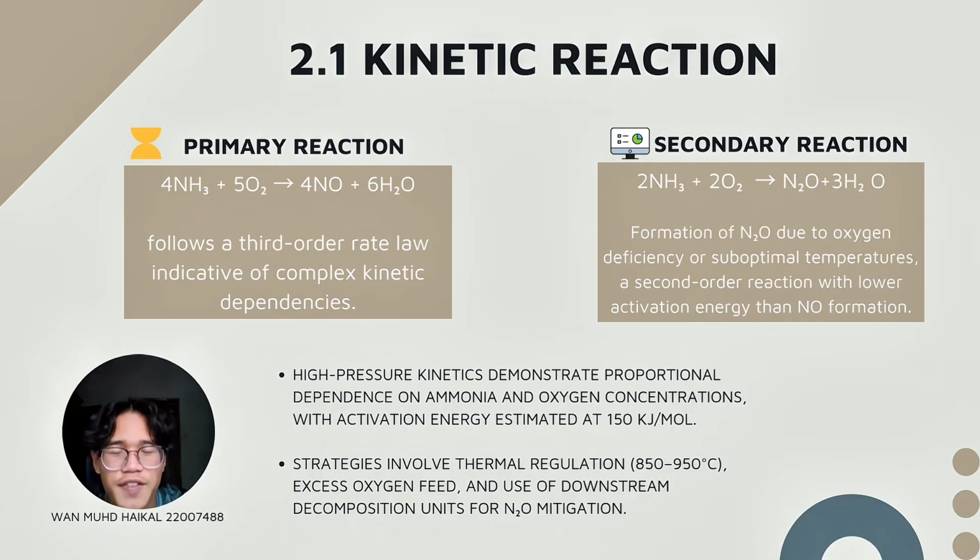Next is the kinetic reaction. The primary reaction of ammonia oxidation involves ammonia reacting with oxygen to produce nitric oxide and water. The reaction follows third-order kinetics, with the rate proportional to the concentration of both reactants.